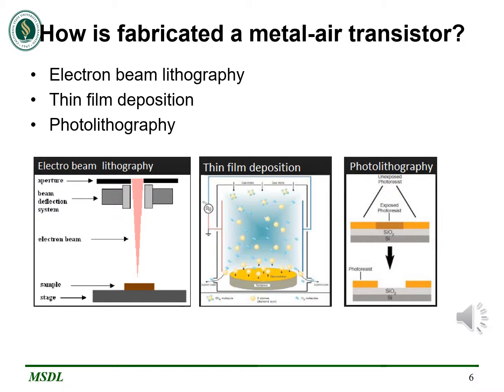To aid adhesion, a 5 nanometer titanium layer was utilized. Both thin films were deposited sequentially by electron beam evaporation at high vacuum in a Kurt J. Lesker PVD-75 electron beam evaporation system. Metal lift-off was performed in a hot acetone bath at 60 degrees Celsius with ultrasonication. Finally, photolithography was performed to create larger contact pads on the nanoscale devices.